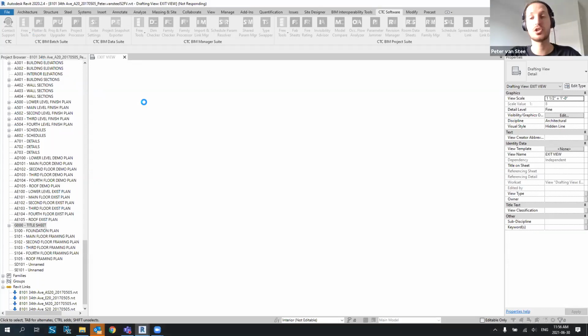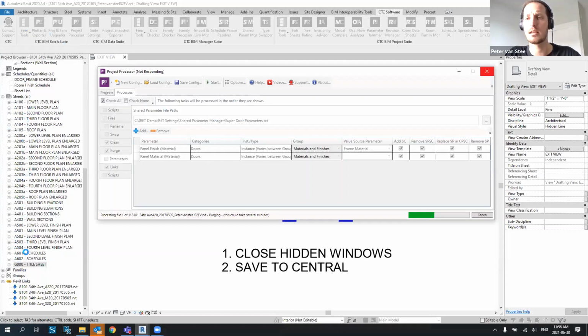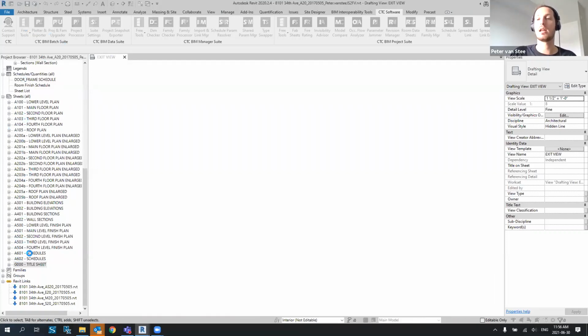Before I get there, let's chat a little bit about what that is actually going to do, or why it's even there. Because, well, I could go through and right-click on a family within the project browser, and say, oh, I want to export or save this one family. But then I have to specify where I want to put that family, and then I've only ever done that one family. Revit also gives you the option to say, well, let's take everything and export everything, an entire library of every single family in my entire project, and just dump it into this folder. Again, it's either all or nothing.